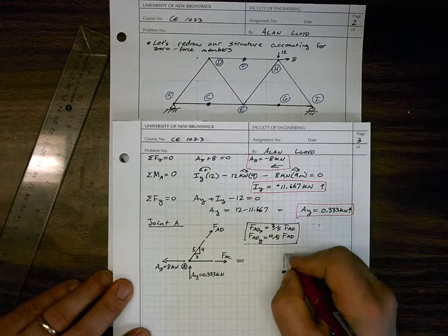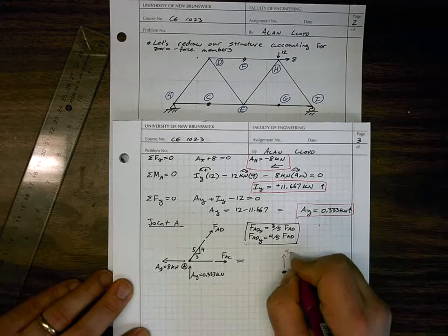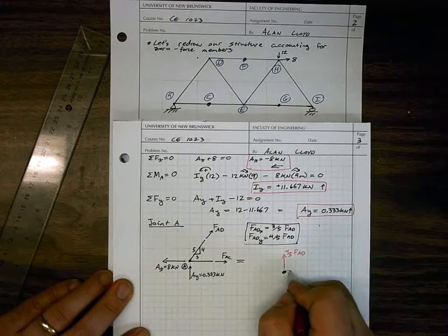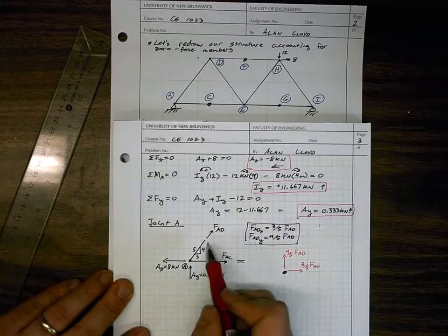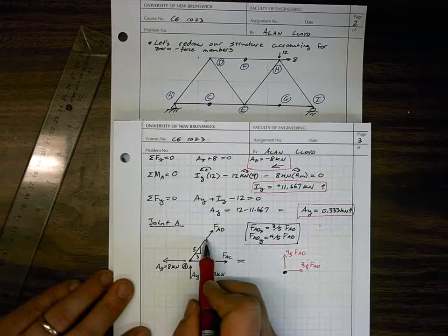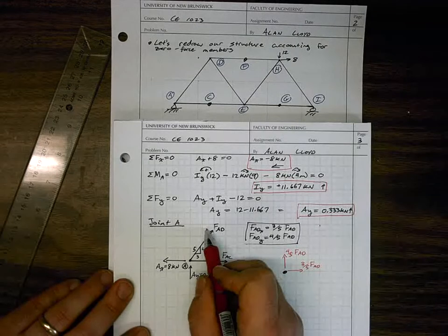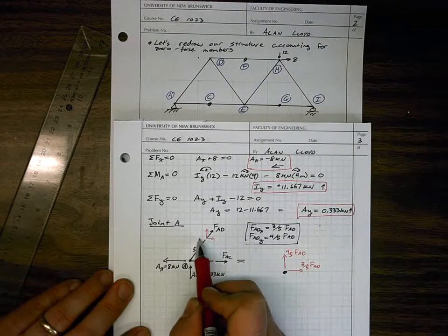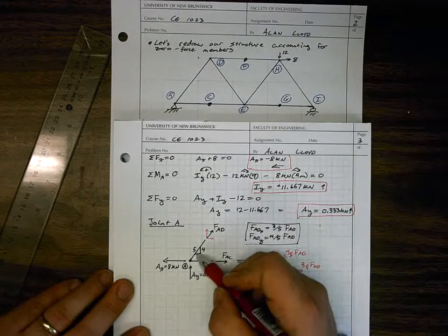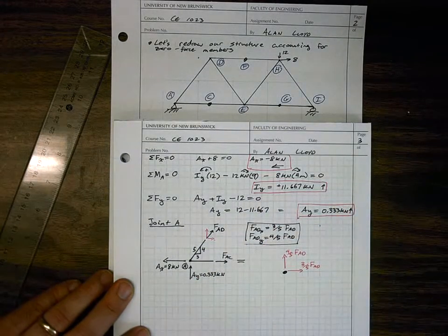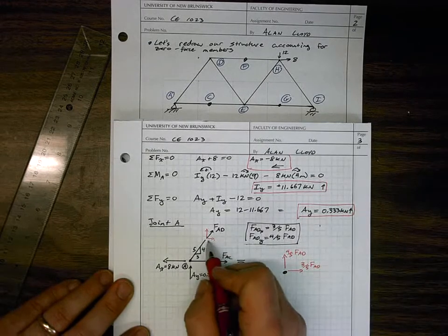We have an unknown force going up of FADY, the y component of FAD. So this is equal to 4/5 FAD. We have an unknown force going this way, the x component of FAD, equal to 3/5 FAD. And we note that if FAD is going up and to the right, then FADX has to be going to the right, and the y component has to be going up. If the x component was to go to the left, the y component would have to go down. The vector sum of these two components has to follow the slope or the angle of that chord. So we know FADX is going to the right and FADY is going up, based on how we drew FAD.